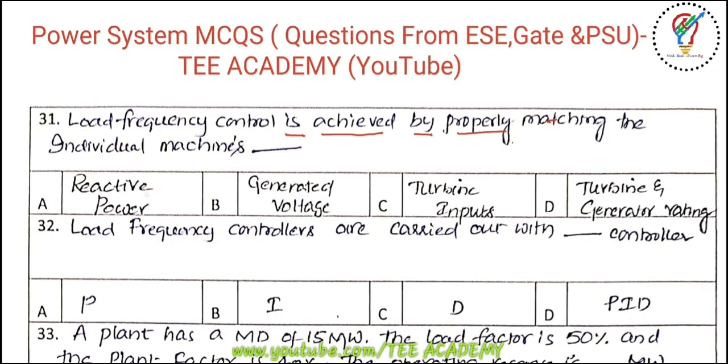The options are reactive power, generated voltage, turbine inputs, and turbine and generator ratings. The answer here is matching the turbine inputs. Why? Because they are going to control the speed. As you know, the relationship is Ns equal to 120 f by P. So C is the right answer for this question.